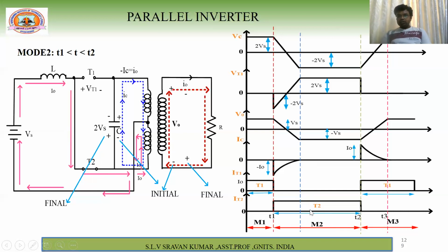So see here, from this point to this point, the voltage across the capacitor will remain the same. The voltage across T1 is this one, and the current here is 0. But T2 is in conduction like this. To turn off T2, even though your polarities are opposite, it is not sufficient. You have to make the current in T2 zero. That is possible only in this case. Only if you give the triggering pulse to thyristor T1 will a reverse current flow through thyristor T2 within a short moment. Then all the charge carriers will be removed in thyristor T2, and T1 will be completely turned on, right?